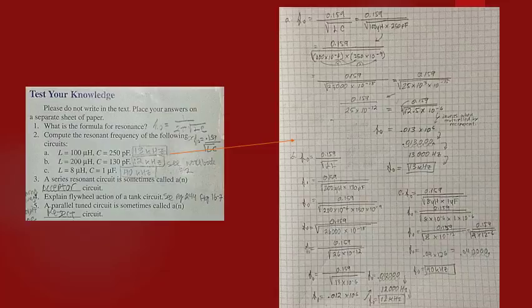Your capacitor is charged to the same level as the source. If it's 5, 4, 12 volts, however many volts it is, that's how many volts your capacitor is going to have. Current stops flowing once the capacitor charges because the circuit is in balance with the power source, so current stops flowing. And then in step 2, we open up the switch for the source.